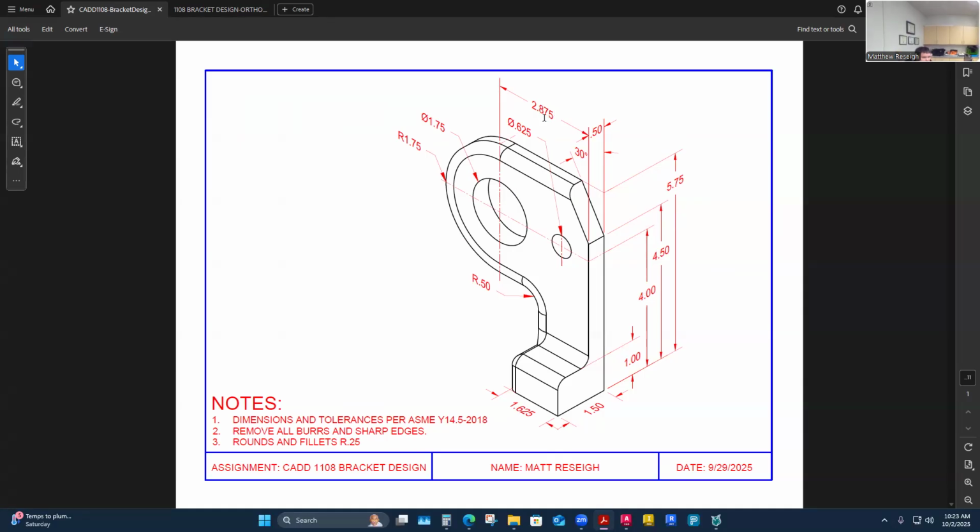So I'm going to go back and I'll show you how you can just spot correct this. Normally on a lot of prints, I probably will have multiple dimension styles that are already preloaded so that I can do this pretty quick. That one's 3, that one's 2, and I can change pretty quick. I only really have one, a 2 decimal place ASME inch. So what I want to do is, like the foot width here, which is actually my foot height in my drawing, and these depths here and that size, I want 3 decimal places.